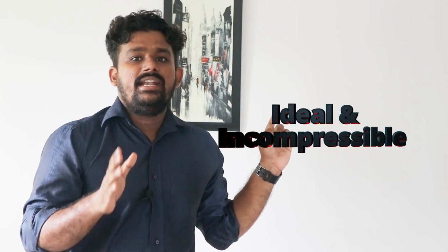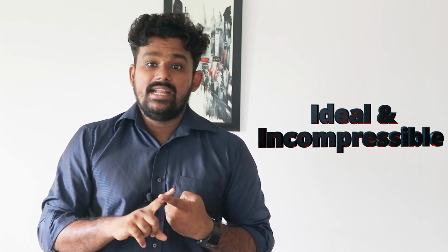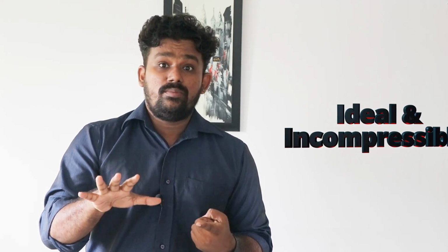First, the fluid should be ideal and incompressible. Ideal means it should not possess any viscosity, and incompressible means the density is constant, as in the types of flow conditions in fluid kinematics. The second assumption is that the flow should be steady and continuous. Steady flow means the fluid velocity properties do not change with respect to time.